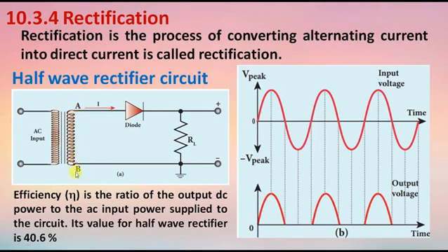Here the B will act as the negative terminal. Now the diode will act as forward biased. It conducts the current, which means it allows the current to flow inside the circuit. The current flows through the load resistor RL, and the AC voltage developed across RL produces the output voltage. That output voltage is V0.